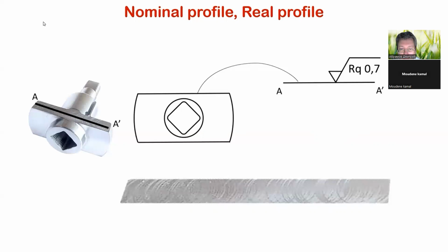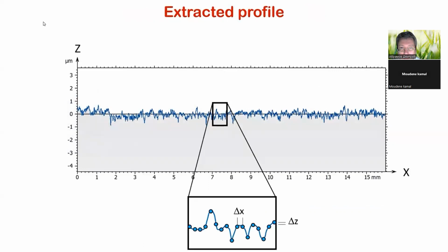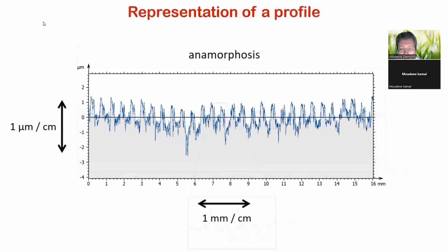Nowadays, it is a digital representation, sampled along x, in successive points, spaced by a constant spacing delta x expressed in micrometers, and digitized in z, using integers, spaced by the value of a digit delta z expressed in nanometers. In the case of a 3D measurement using an optical profilometer, an image of heights is obtained where z is a function of x and y.